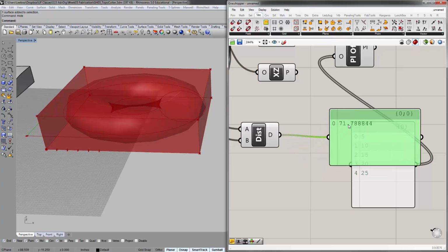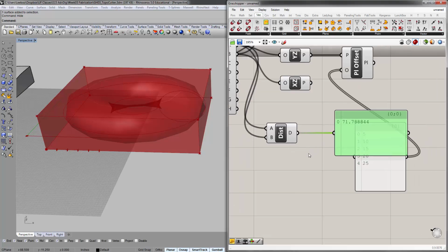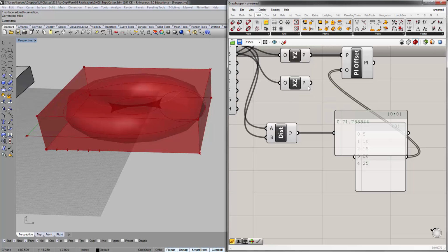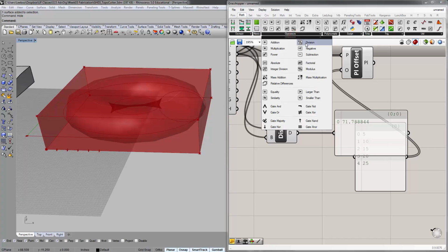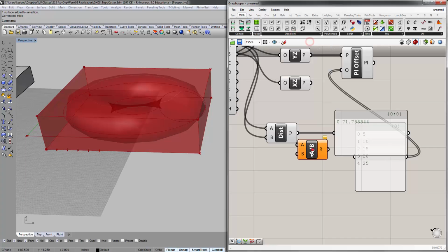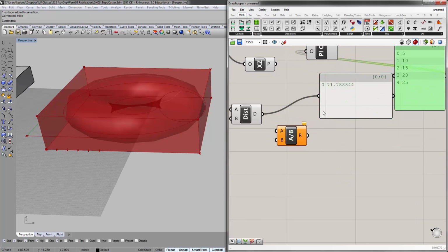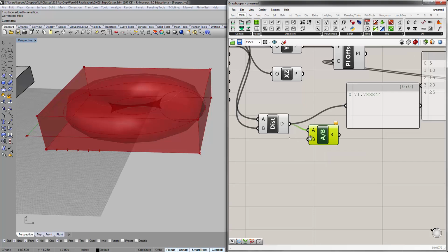It can be a fixed number or a changing number if we use a slider, right? So double click and divide, and it's actually this one, but to find it you can go to the second math panel, operators, division. This is simple enough. Give it the first number, which is this, and then give it a second number here.